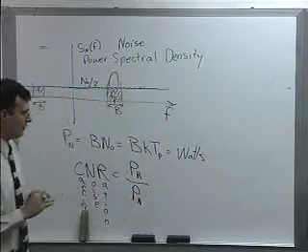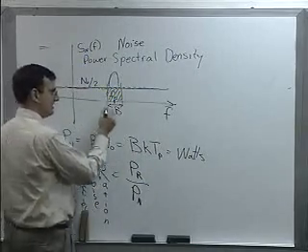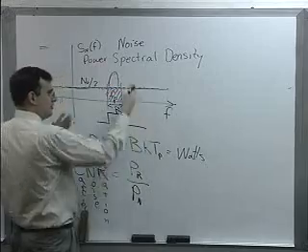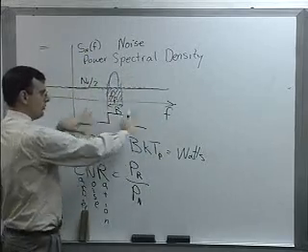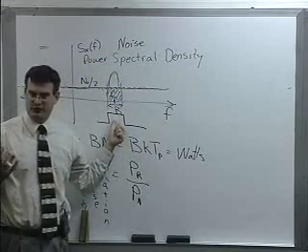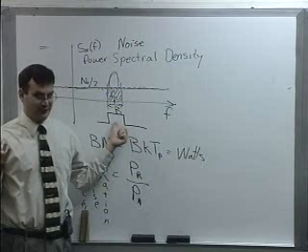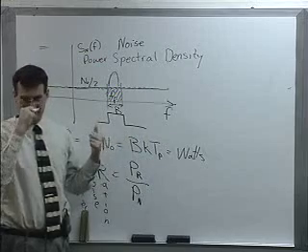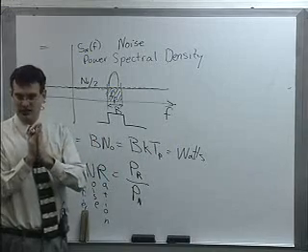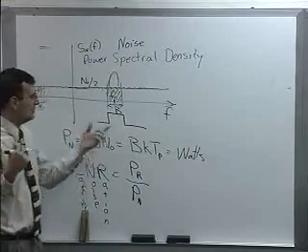Now, a couple of notes before we get into our noise figure analysis. One thing I didn't mention last time is that this analysis assumes that you have this perfect brick wall filter that you can drop your signal plus noise through and get rid of all of the out-of-band noise. Of course, anybody that's ever tried to build a real filter in real life, outside the world of MATLAB, would realize that a causal filter can never look like this. In other words, a filter that has no latency and doesn't have a response for t less than 0, when the signal can't anticipate the signal hitting it. You can't have a perfect brick wall.